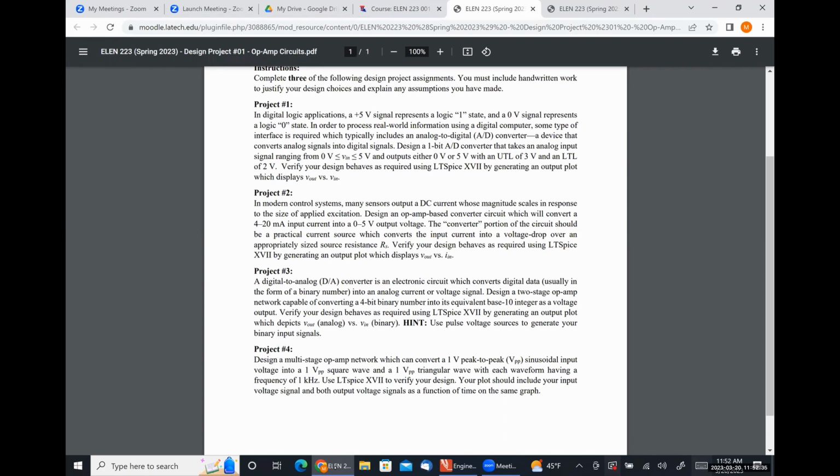And if you get to simulating these things and it's not behaving like you expect it to, instead the voltage or whatever is just gradually getting larger and larger and larger, it's because you're not letting your energy storage elements discharge enough between cycles. Can't just throw any resistor and capacitor in there and expect it to work. I know. You have to think about things, the horror of it all.